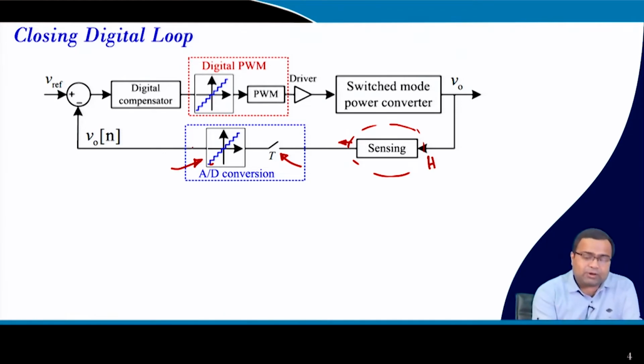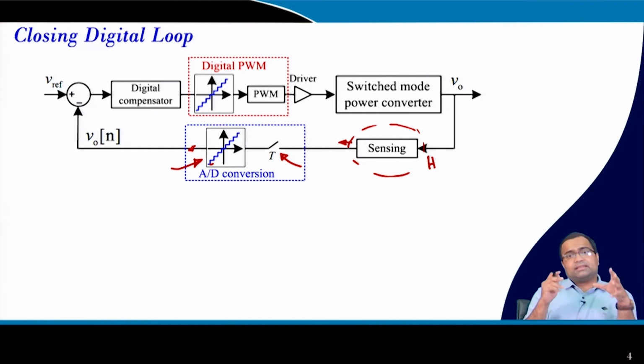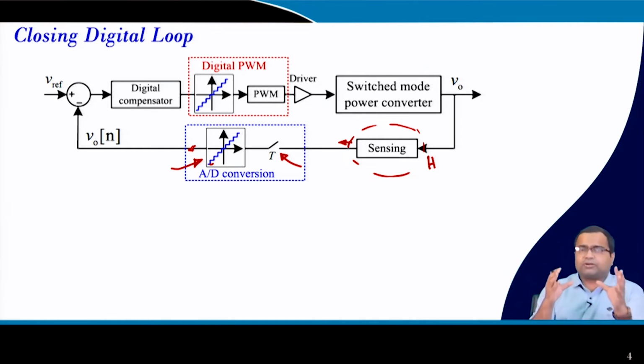After this quantized voltage, there generally has to be a coder, which converts the output into a code, because it will be a stream of binary numbers that can be represented either in 2s complement, offset binary or straight binary.